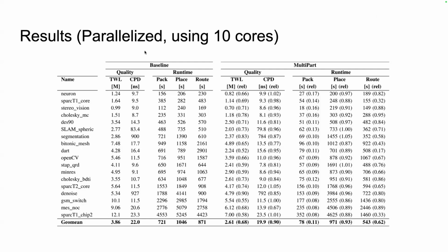So this is based on VTR7, which did not have the best quality, I guess, and the packer was very aggressive, incredibly dense. The packer was a big thing; the packer was too aggressive, so dialing that back on unrelated logic made a big difference. So essentially, a lot of the quality benefits here could be attributed to the fact that they made the packer less aggressive and less dense.